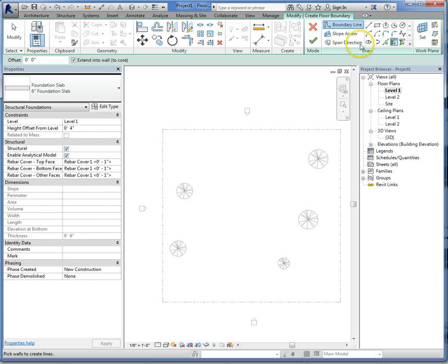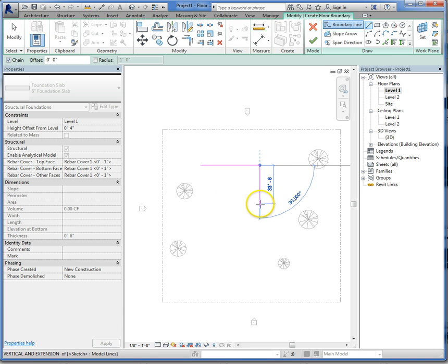Okay, so next we have our basic drawing tools here. So I'm going to pick line, and you would start to draw the foundation of the house you've planned out. In my class, we're doing a 1,000 to 1,200 square foot small house as a first project. So you would do that, just kind of get the line going the right direction. You can type in, and it's going to be feet by default.